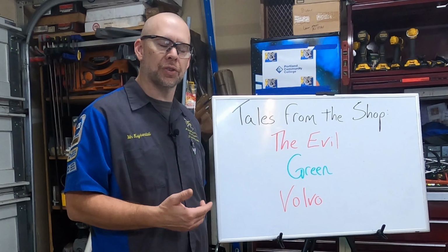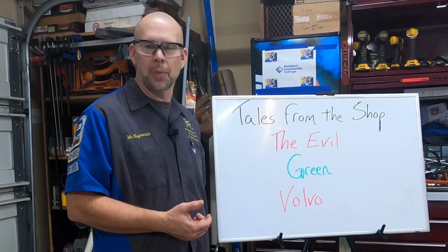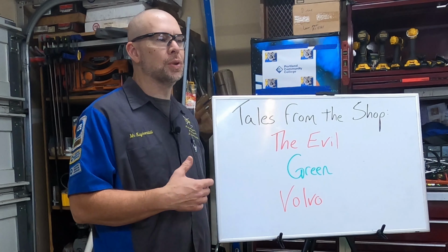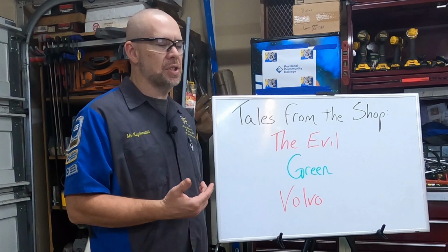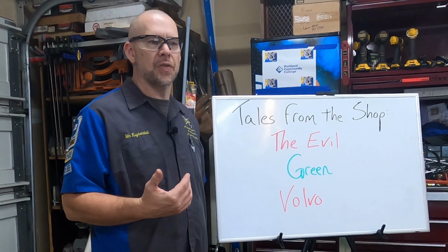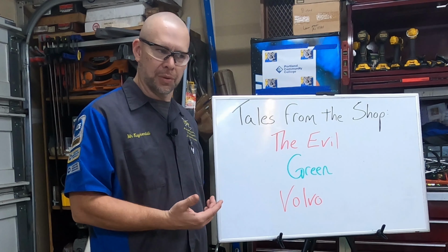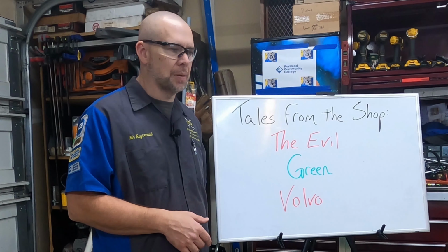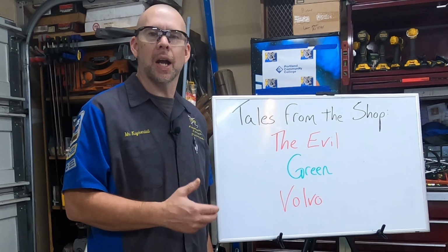Now, since the fuel filter didn't get changed on the job, that's the first place I went. It's easy to get to, and fuel filter tests are simple. You blow through the fuel filter and you see if it blows through clearly, you know it's okay. If it's difficult to blow through or it takes effort to blow through it, then your fuel filter is restricted.